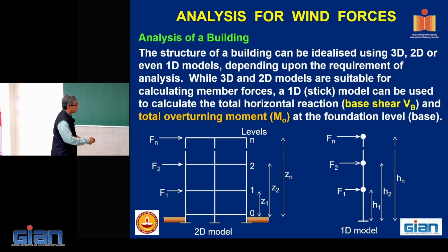Now, even before jumping into a structural analysis, I tell the students to conceive the building as just a stick model. What is a stick model? I am forgetting the two-dimensional distribution of the floor. I am thinking as if it is lumped at one point, and I am just interested in the vertical distribution.